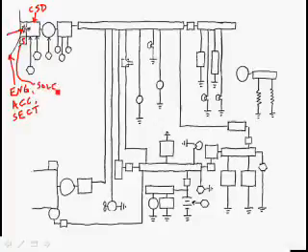S is for solenoid. And that's a solenoid that can retract the CSD gear into the CSD if you need to disconnect it. The CSD, we might have a temperature gauge, as previously discussed, and an oil quantity gauge. Actually, it would be quantity of hydraulic fluid.